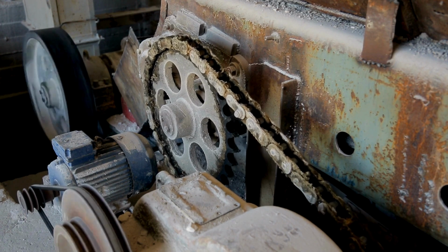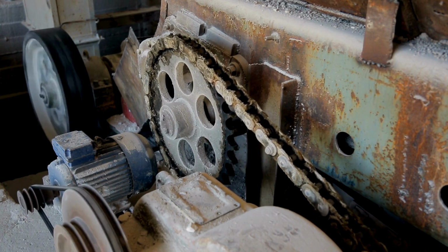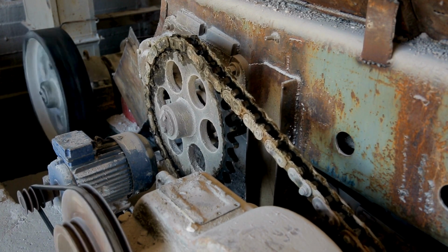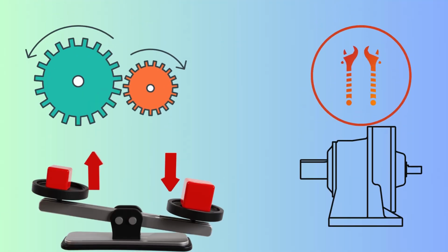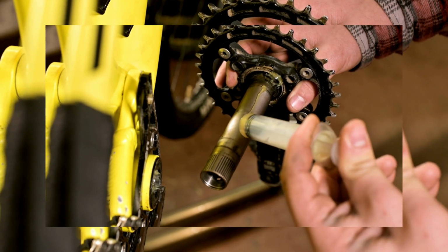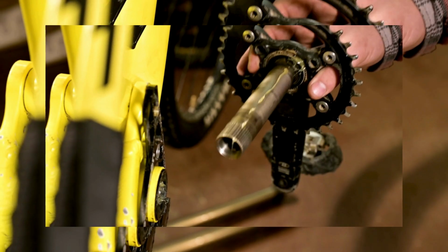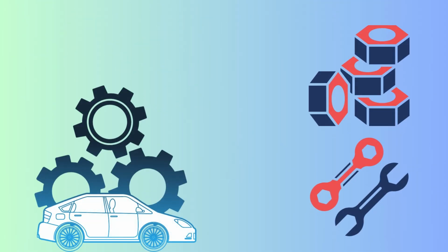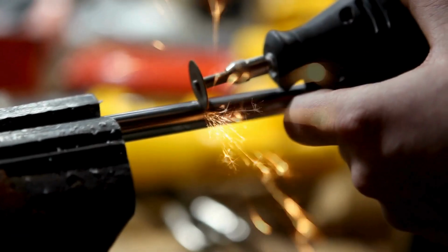The torsional stiffness of a gearbox is influenced by the deflections of bearings, shafts, gears, and the gearbox housing. Torsional vibrations can occur in power transmission systems, especially when using rotating shafts or couplings. These vibrations can be detrimental and lead to failure if not controlled. When designing gears, it's crucial to consider the torsional stresses and deflections to ensure the gear system can withstand the applied loads without failing. Repeated torsional loads can lead to fatigue failure in gears and shafts. Proper material selection and design practices are necessary to mitigate this risk.